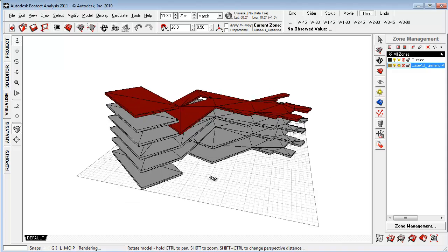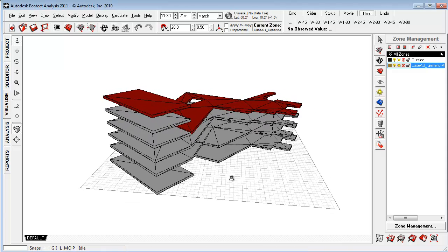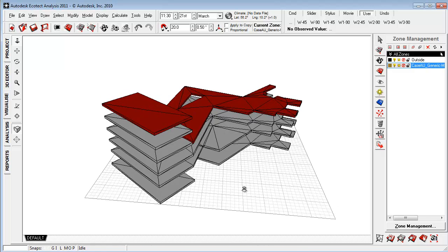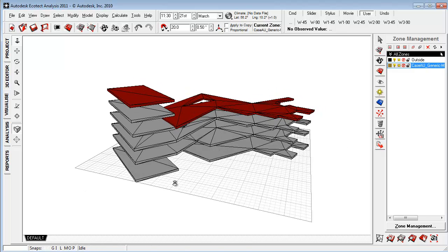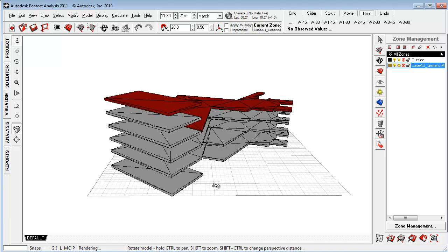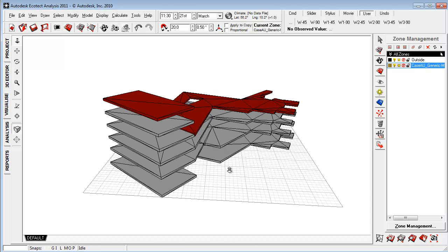I've now opened the conceptual environment within Ecotech, and I want to show how we can optimize two different kinds of geometry. Here there's some real building geometry, some roofs and some floors that I imported from Revit. It's a really good methodology that I sometimes use to split up the model, to import the floors and the roofs by themselves, and then import the walls without the windows.